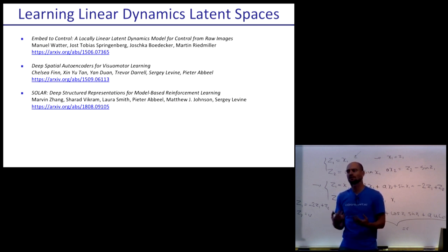And if the latent space is linear dynamical and still models the original space pretty well by going to latent and then back, then that means you implicitly found the transformation without explicitly solving the PDE. You found it by training your system to be good at predicting the future, and directly that way found a transformation that makes your control problem simpler.